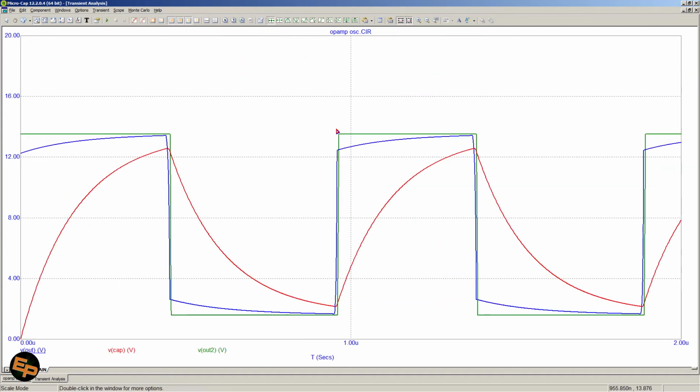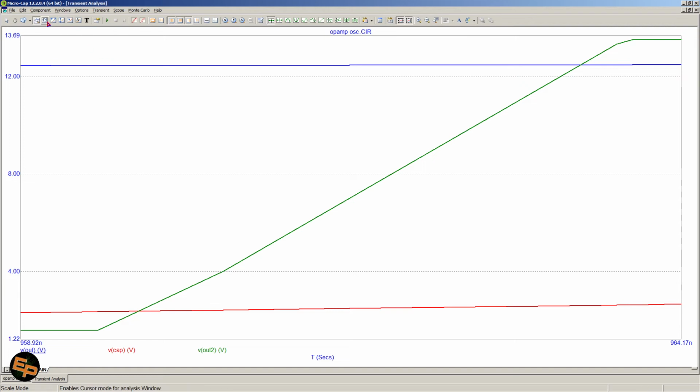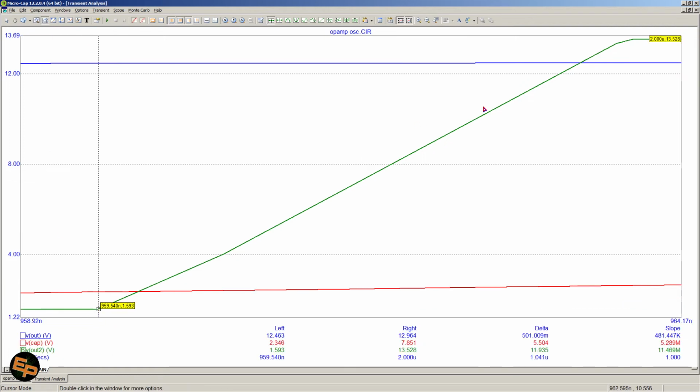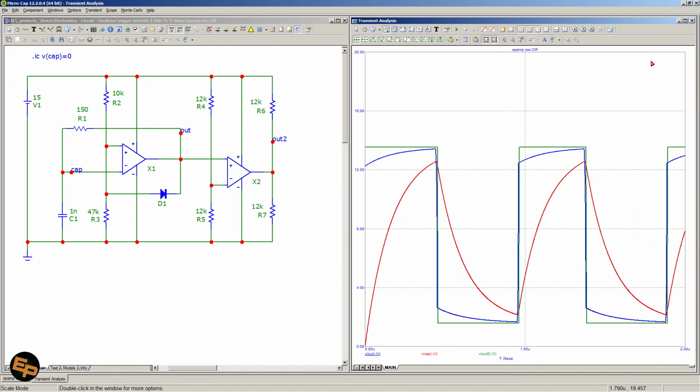And if we zoom in to see the rise time, we would pretty much get something similar. So let me put the cursors. See, also 4.2 nanoseconds rise time. That's pretty fast, and obviously that's a nice thing because that's exactly what we want.